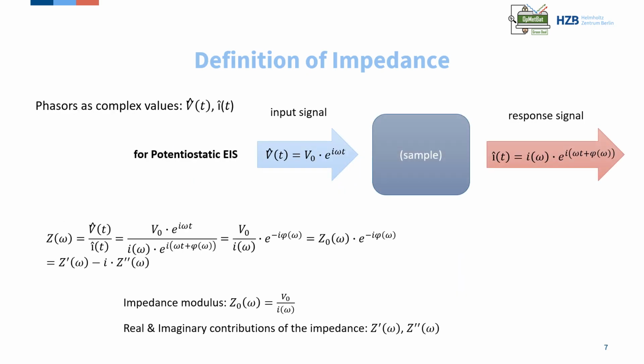Sinusoidal signals of coherent behavior can also be considered as phasors with rotatory oscillations, and this results in exponential relations, which provide real and imaginary contributions in complex numbers. Consequently, impedance values are complex resistance values, exponentially dependent on the angular frequency. The response signal will also have a frequency-dependent amplitude and the contribution of the phase shift.